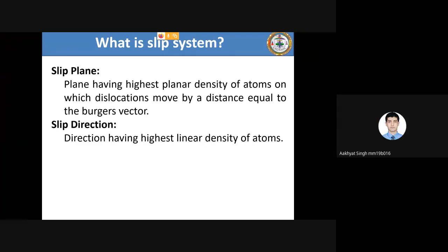No, can you define it? I slightly forgot that part. Sure, no problem. See, the Burgers vector is nothing but the minimum distance traveled by a dislocation on the slip plane in the slip direction, right? What is a dislocation first of all? Dislocation is a one-dimensional defect, and dislocations are carriers of plasticity. When you deform the material plastically, dislocations are there to manifest that, plus the strain energy. You introduce a lot of strain in the material, and dislocations will obviously accommodate that strain, right? Correct, that's the physics behind this.